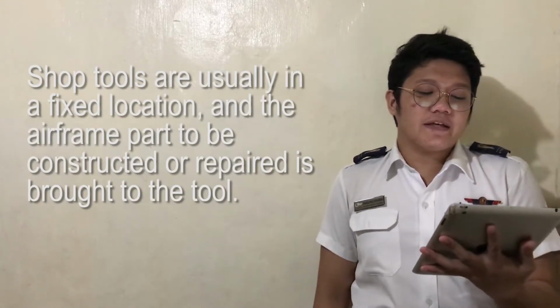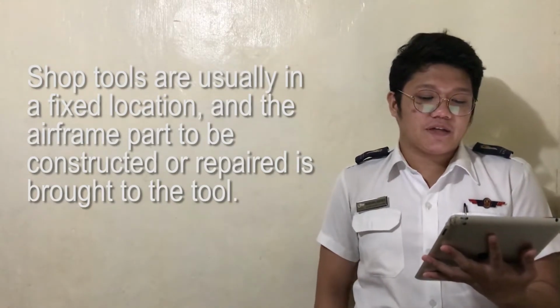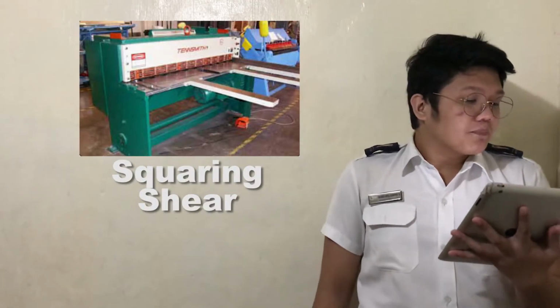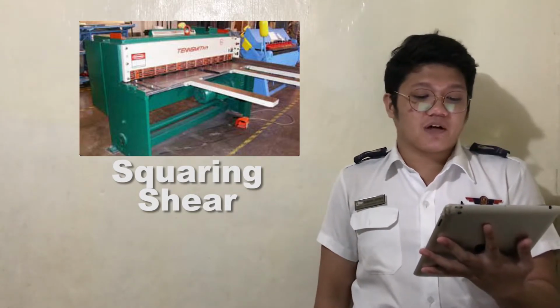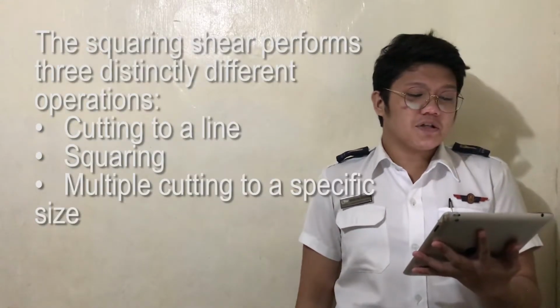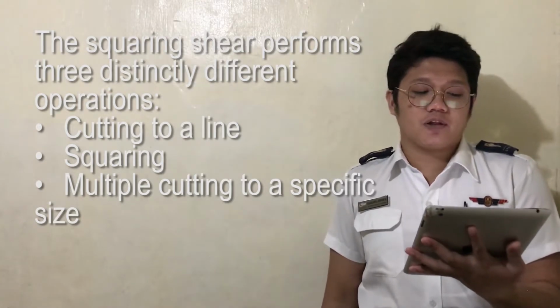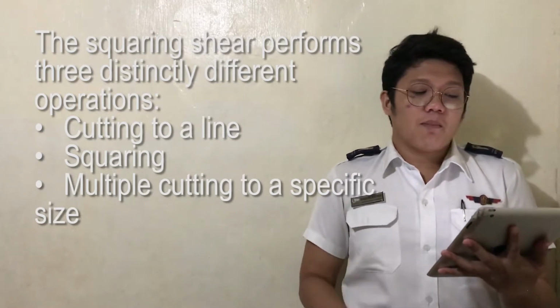Shop tools are usually in a fixed location. The airframe part to be constructed or repaired is brought to the tool. Our first well-known shop tool is the squaring shear. The squaring shear provides the airframe technician with a convenient means of cutting and squaring sheet metal, available in manual, hydraulic, or pneumatic mode. The squaring shear performs three distinctly different operations: cutting to a line, squaring, and multiple cutting to a specific size.